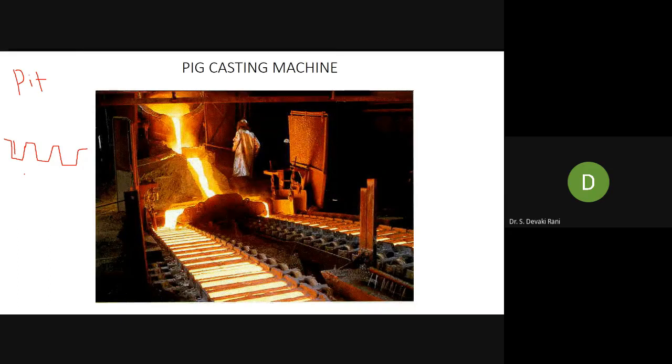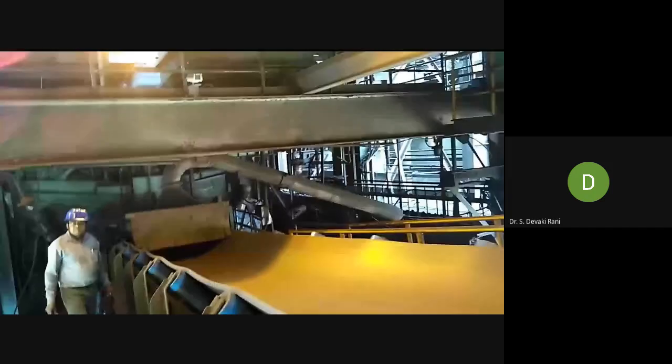Suppose I will give you a hint. What I told you, pit casting was done in olden days. That was the first point I told, if you remember. Second, in the olden days, the blast furnace need not be synchronized with the steel making. That means the steel making shop need not be ready once the blast furnace metal is coming out. That means you can charge a solid pig. Okay, you understood now? Confused about what the key point is?